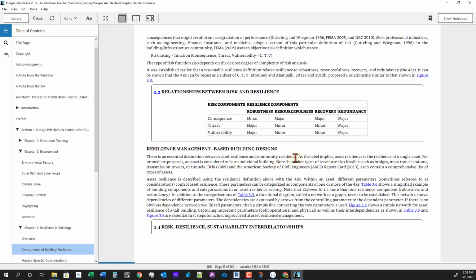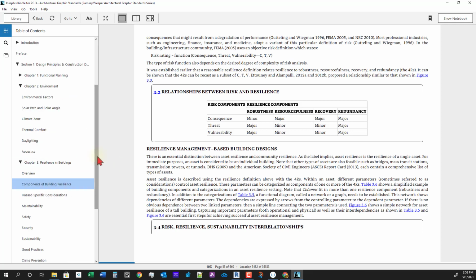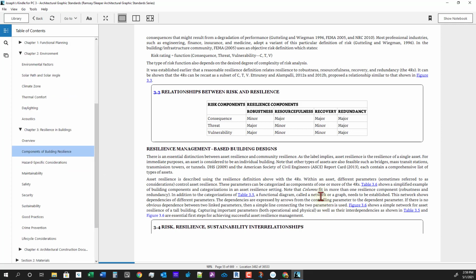So this is really talking about how your building is in relation to any of the elements, whether natural or man-made. So it's going to talk a lot about seismic design. Wind does play a big factor in building. There's suction. When wind goes around a building, it actually will try to pull any finish off because it's causing some suction at the corners.